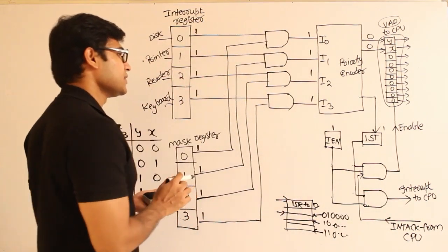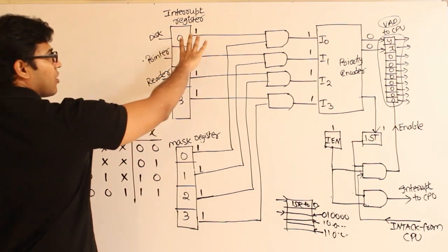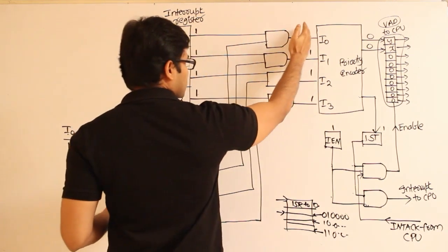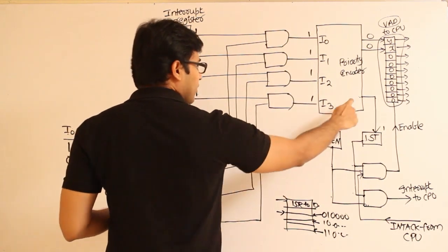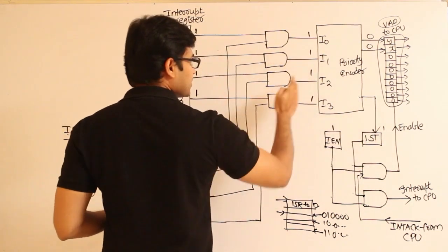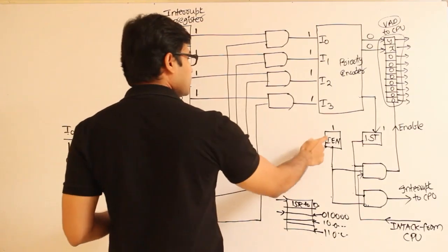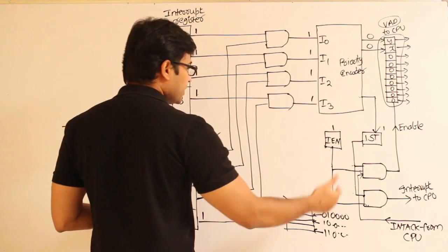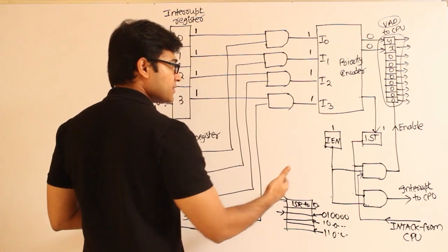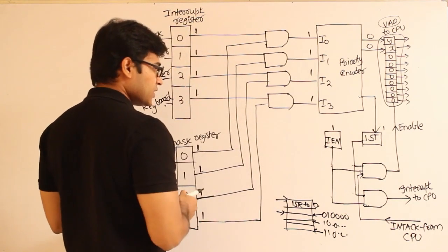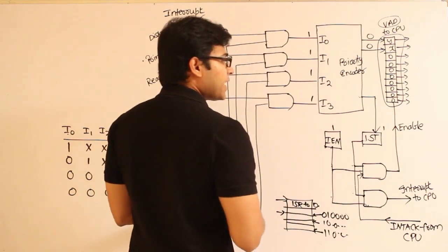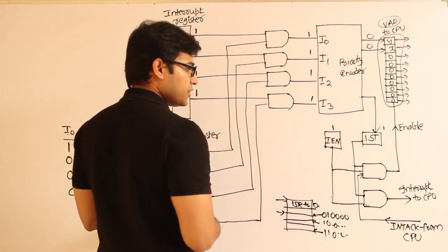So first of all, all the devices request some interrupt service, and then all of them have shown their interest here, right? Now first this one will show that someone wants the interrupt service routine, and this will show that the programmer is willing to be interrupted. If both say yes, only in that case will an interrupt be sent to the CPU. As a response, the CPU will send the acknowledgement, right?